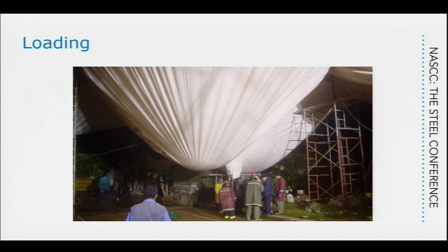Yes? The Denver with the snow, what happens in Denver with the snow? Okay, so part of the design of membrane structures is that when you establish a shape, a form that you like, you have to make sure that you don't have any what we call flat spots. You always want your rain and your snow to slush off.